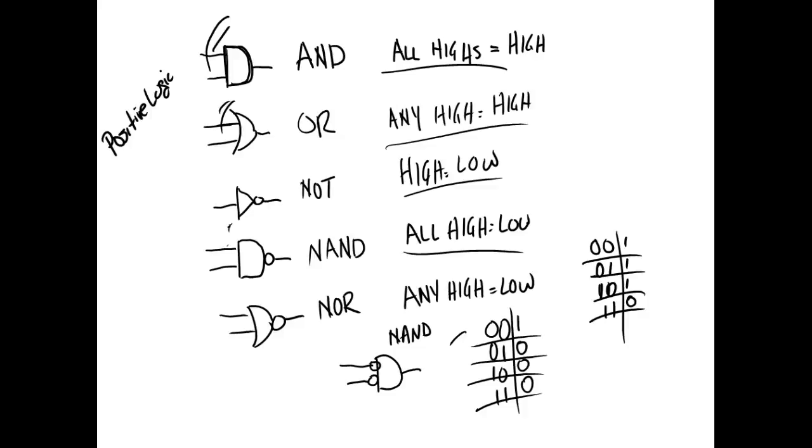So what I'm trying to tell you, don't jump on the bubble on the output as being a NAND and an OR. This is called a negative NAND. So, we'll talk about these later. So don't say, well, if it's got a bubble on the output, it's a NAND and an OR, right? You understand, or not, it's going to screw you up.